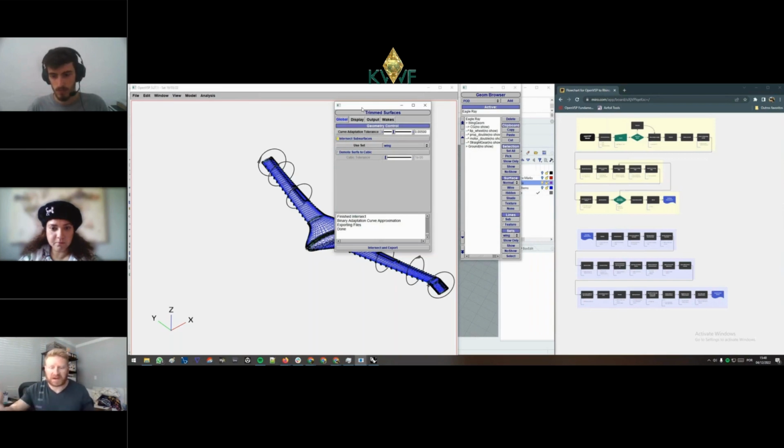So if it's just an average where most of it is really accurate, but you have a dip somewhere on, say, the adverse pressure gradient on the upper surface, you could end up with premature separation at high angles of attack. So just because it's really good, maybe we can try and clean it up and make that zero. It'd be really nice, but